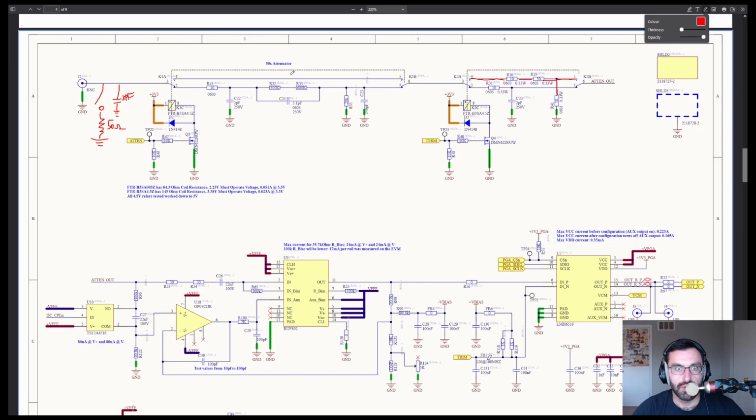And then this path, the 1x path, needs to equal the 50x path in capacitance, which is about 7 picofarads. How does that distribute to the 1x path? Well, we purposely add the 2 picofarads to the about 5 picofarads of the buffer and associated circuitry.